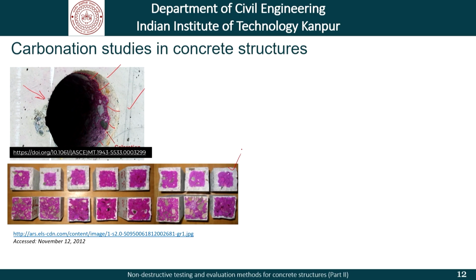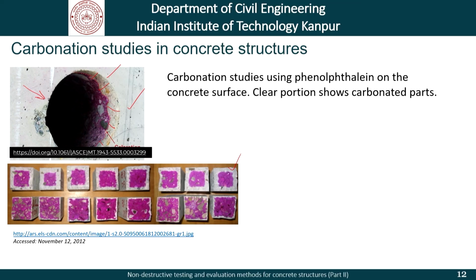I would only like you to remember and note that this depth that we measure here, or for that matter in laboratory studies at different locations at different points in time using different concretes and so on, it's very difficult to come up with a single number x which will be the carbonation depth at a given point in time. When we had talked about carbonation in the previous module, we had said that as far as the design is concerned, as far as the management is concerned, we need to ensure that the carbonation depth x at service life should not exceed the cover provided.